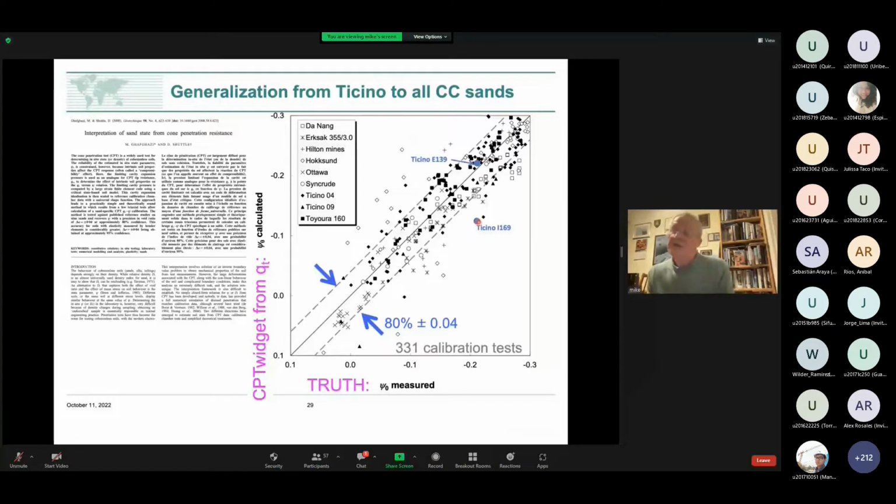Yet the reported tip resistance varies by a factor of 2. So I think a lot of the scatter is actually reflecting testing precision in chamber testing. And the important thing to us was that our trend line was unbiased. There's equal amounts of data above and below, and we're on a one-to-one plot.